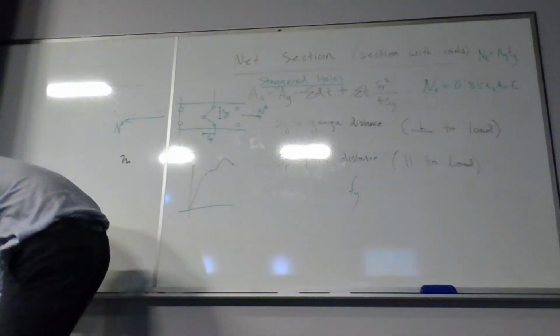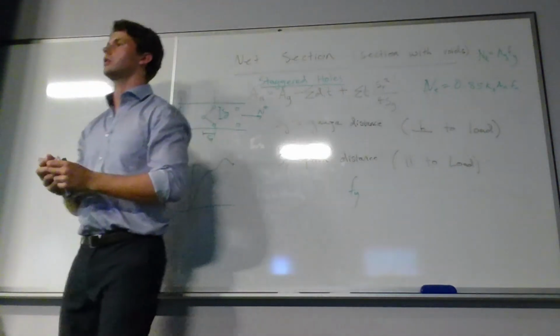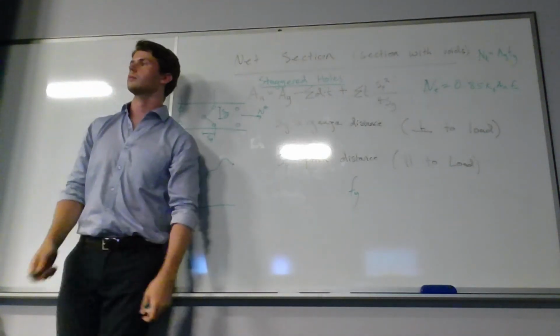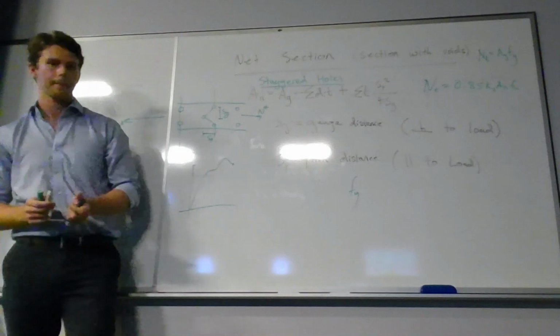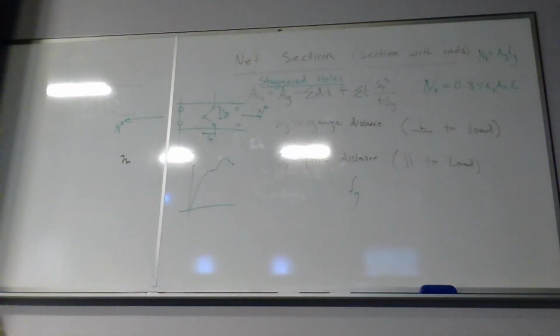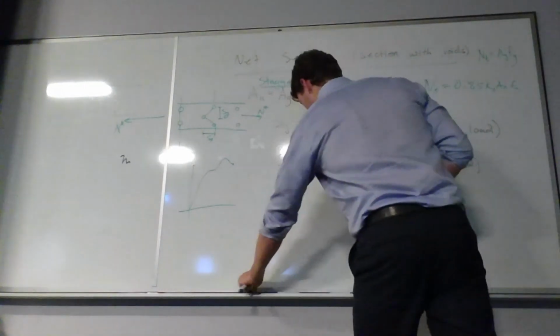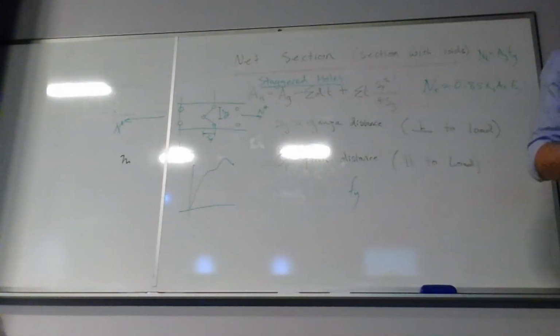Just a bit more on that, you can think about the difference between yielding and ultimate. Yielding is, think about it as it hasn't separated yet, right? If you take steel and stretch it high enough, eventually you'll start to neck. As you stretch it out, it becomes like bubble gum. That's yielding, but it's still intact. Ultimate is when it just snaps.